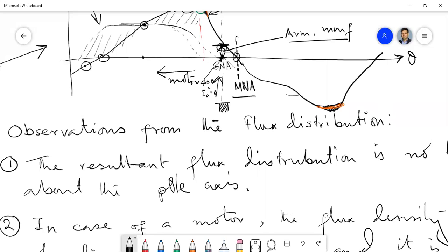But these are all ideal things. Due to the armature reaction, at the point where the flux is supposed to be zero, now there is a finite flux over there. So due to this finite flux, as the coil is rotating in this flux, there will be some rotational EMF in the coil. Now the coil having this rotational EMF is connected to the commutator segments. And between two commutator segments, if the voltage is going beyond 30 volt, then there is every possibility of sparking.